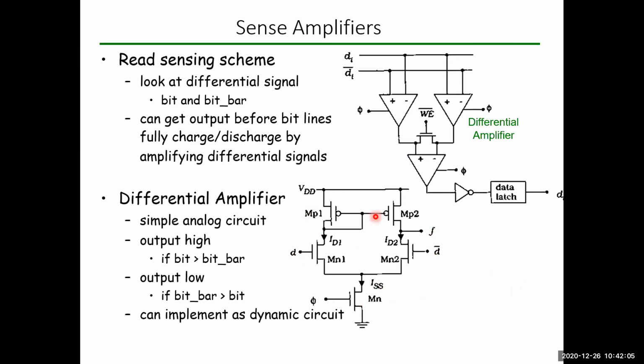So now this is what we call a mirror circuit. In analog electronics, if you have studied, you will understand this one. The mirror is done between these two. The cross connection: the gate of the first PMOS is connected to the drain of another PMOS. So this is how the differential amplifier looks.